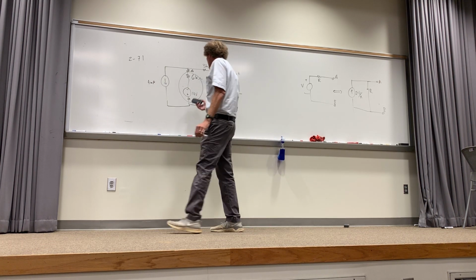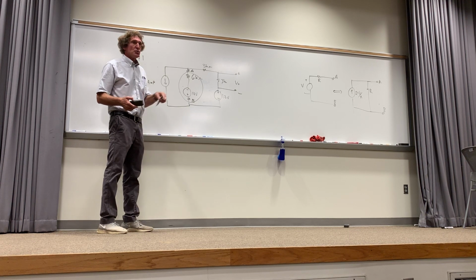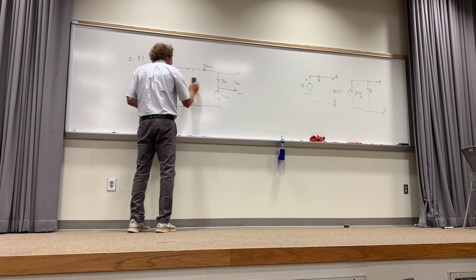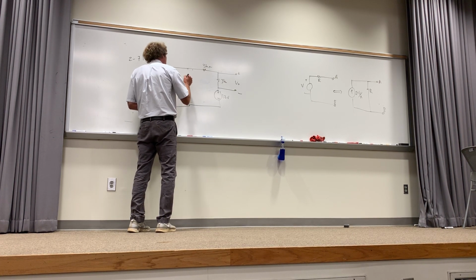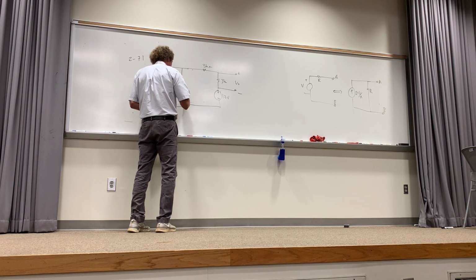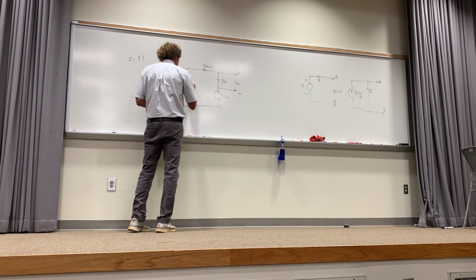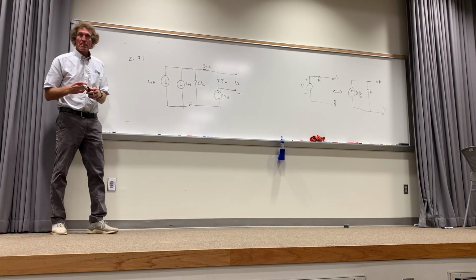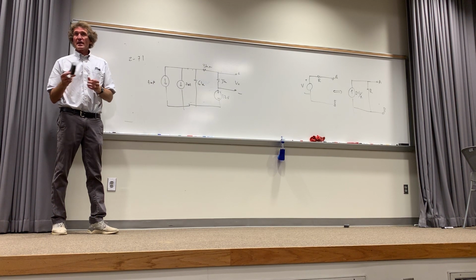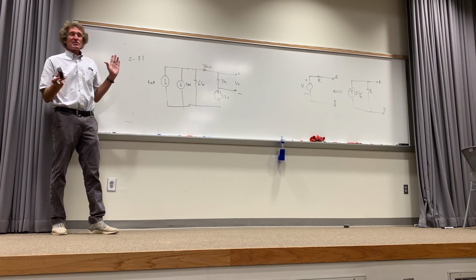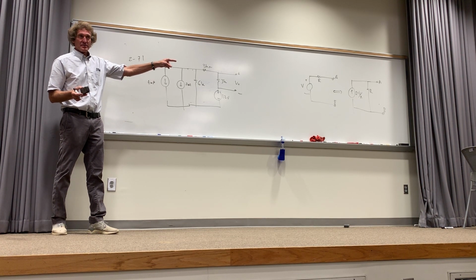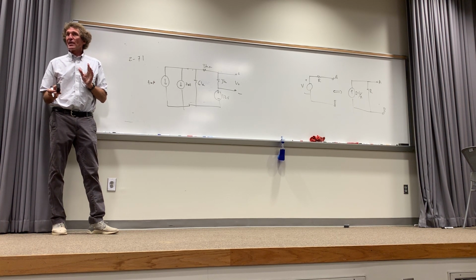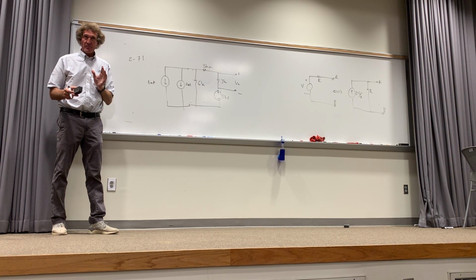All right, so I'm going to have a current of 12 over 6, or 2 milliamps down, in parallel with 6K. That's the first thing I'm going to do. So now I have a current going this way of 2 milliamps and a resistor here of 6K. Can you appreciate what I'm doing? This is a good problem. I'm glad you brought that to my attention. Are you with me, everyone? It's a little different. The thing's not bent like that, right? And it's right in the middle of the circuitry, rather than at one end. You follow me in this class?